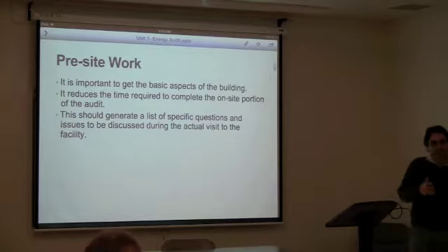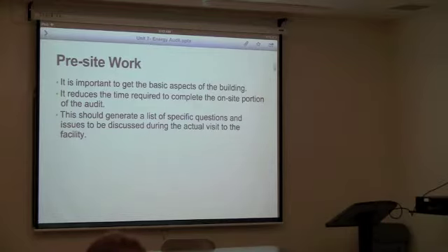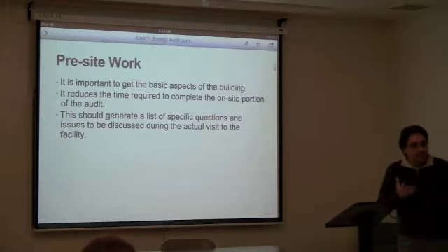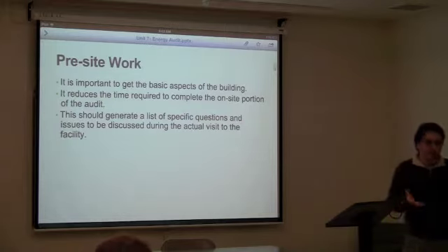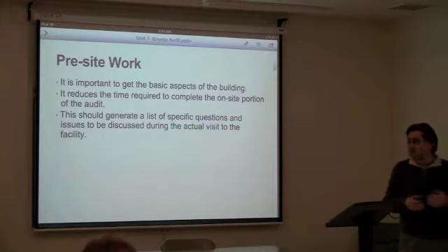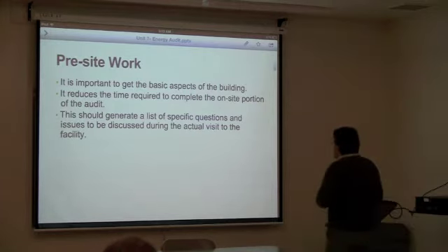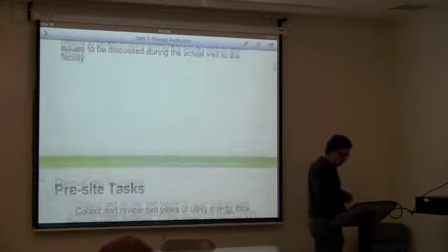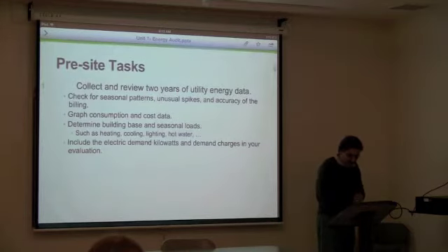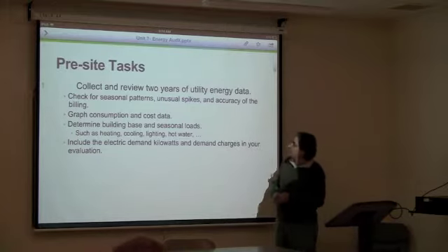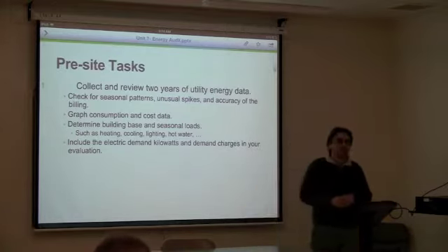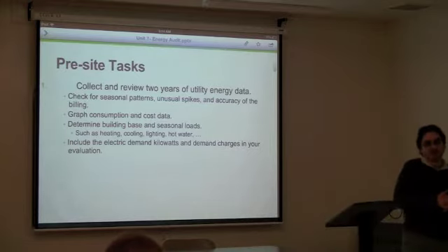You have to know what your building is like, what the orientation of the building is, what the geographical location of the building is, find out the bills that you have for the past 24 months, get the weather information from outside for the past 24 months, season-wise, and try to understand basically the relationship between your building and your bill. And graph the consumption, try to put all the information you have on a graph.